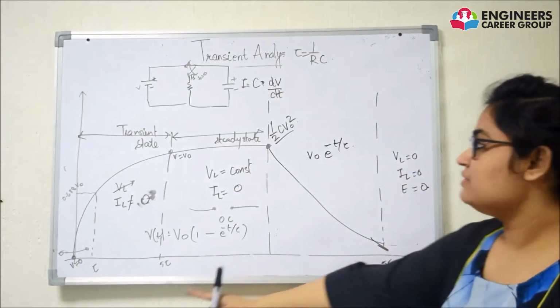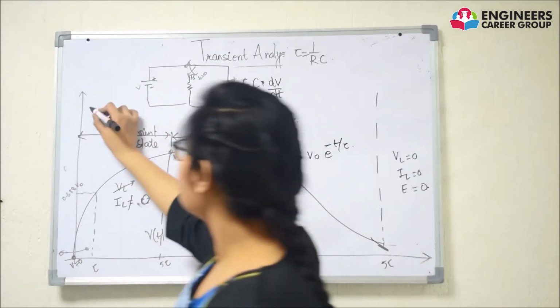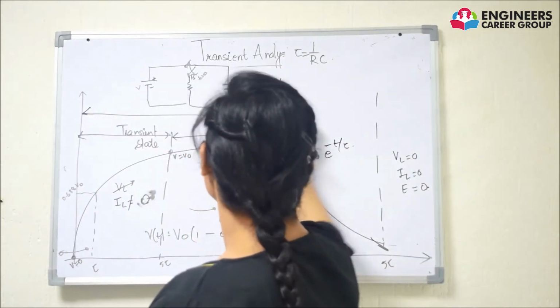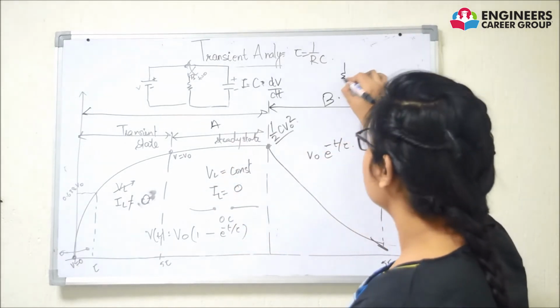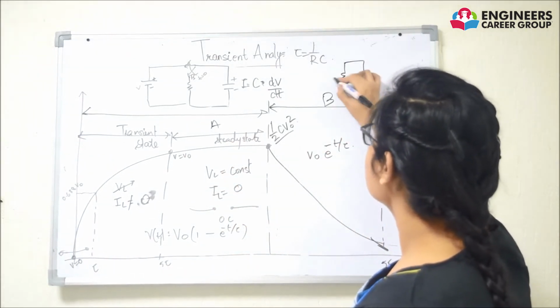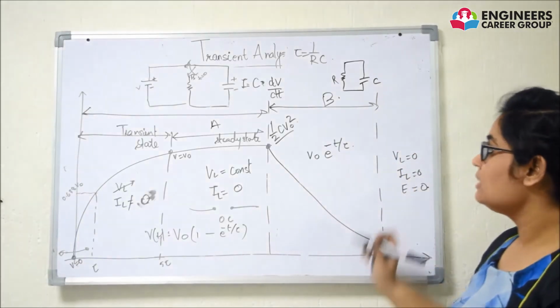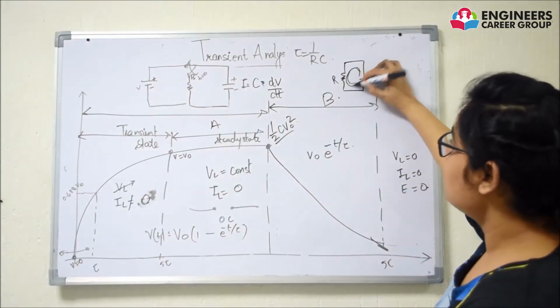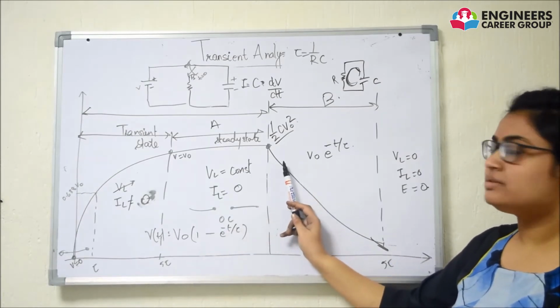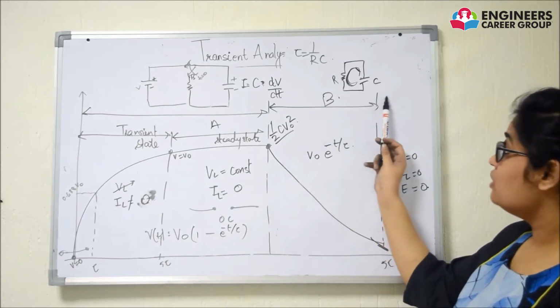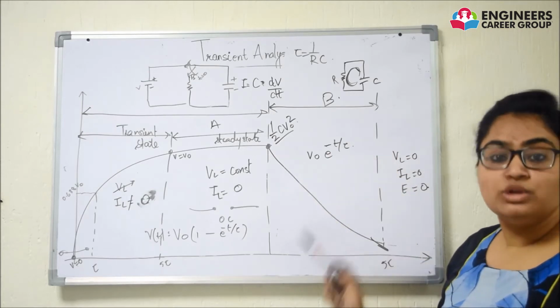Now the capacitor, after complete charging, when this is my switch position A, similar to the inductor, and this is my switch position B, this circuit becomes a source free RC circuit. The whole energy is dissipated across the resistance. I have already discussed that initially the inductor will act as a current source. Now we can see that the capacitor will act as a voltage source.